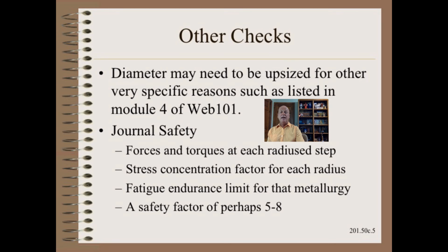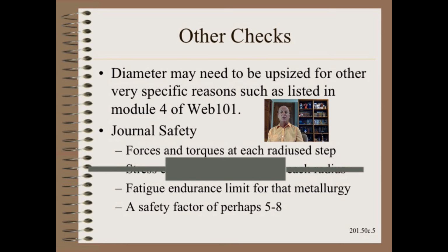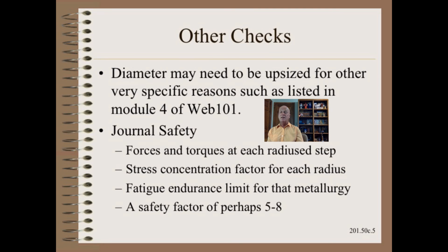Even those who are not tasked with such weighty details as safe design can still be on the alert. A pretty sure sign of an engineer who did not go to school is having bearing housings not nearly touching the heads of the rollers to keep the bending moments to a minimum. We do not want to move the bearings to the frame. We want to move the frame to the bearings. Since spindly journals with long stickouts are not uncommon in some converting machines, it is clear we cannot always assume that every designer went to school on roller design.